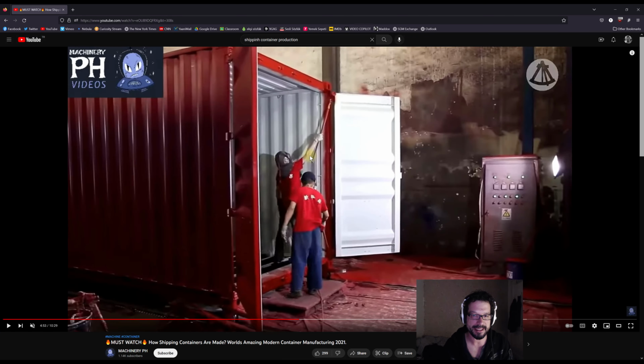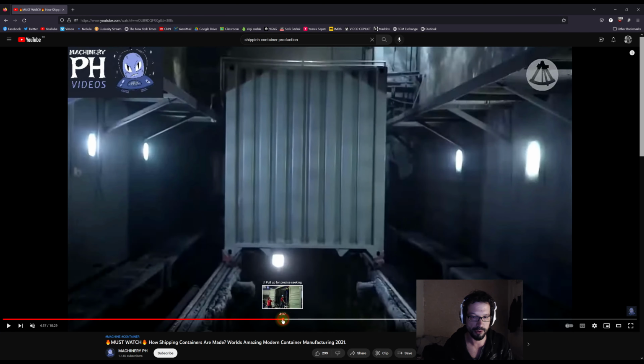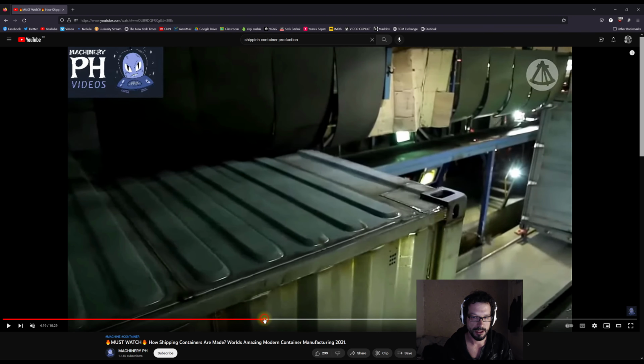Now it doesn't look anything like this or before it was painted, but if you look at the corners, these grind away areas, so this thing is welded, and after the welding operation is complete, they grind those welds to reduce any type of protrusion on the surface, and through that grinding operation the layer of oxidation is scratched away and this shiny metal is revealed from underneath.